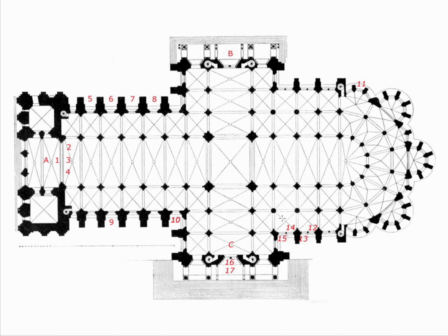Then you start to think about and look at the columns in these cathedrals. And you start to see that, yes, even the biggest are biaxially symmetrical. We can see how the biggest ones then are taking on the most load. Therefore, they have the most area. You can actually see that these columns are resisting buckling to the outside. So they have their amount of area pushed to the direction in which they know that they're most likely to buckle.